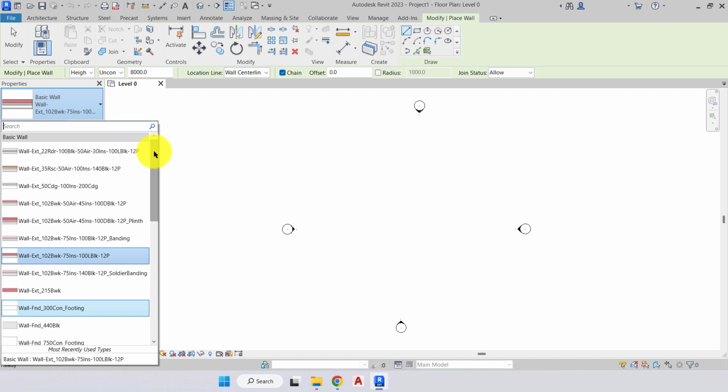So within the library, there's various different regulated wall types, and also in our doors and windows and everything else. They've all been created using the regulations that apply to those certain components. Obviously, the UK regulations apply to the UK, but we'll use them as a basis for you to understand. And then whatever country you're currently in, you need to then create your own wall types applying those same regulations. And at the end of this course, you'll be able to do that quite easily.